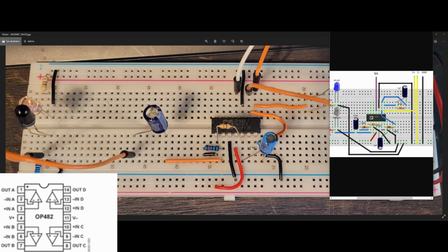And then from here, so that's the change I'm going to make right now actually. I'm going to take out this black wire, and then I'm going to take the capacitor and just put it into ground. That way it's a little bit simpler. We have one less wire in our circuit that we have to deal with. It makes things a little bit easier to see.